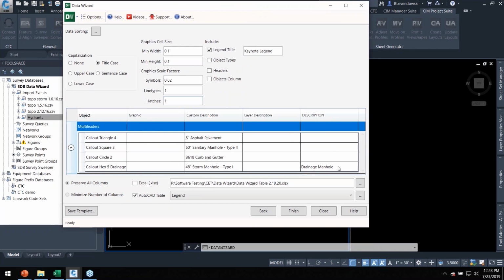And it looks like in one of my multi-leaders there are blocks, as smart as possible. So you can have this attribute data within your multi-leaders as well. You can have it within your blocks, and you can read not just layer name. It makes it pretty smart. Names, all this kind of information can pull through.